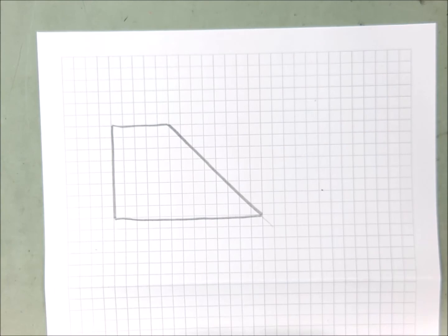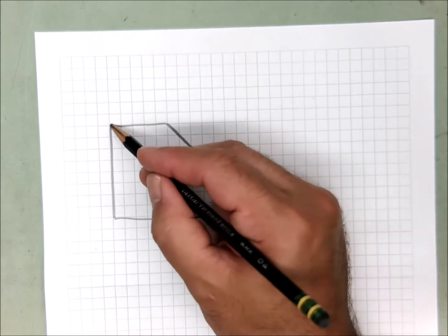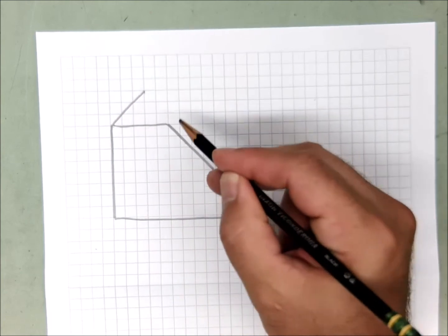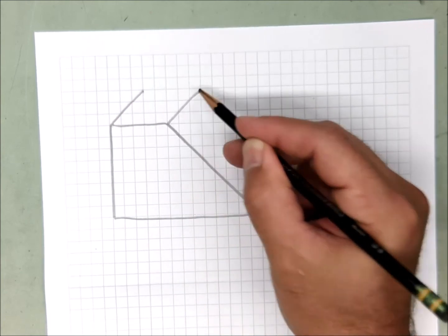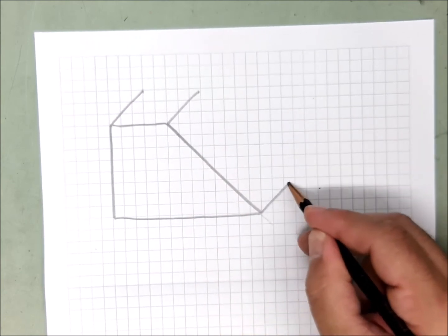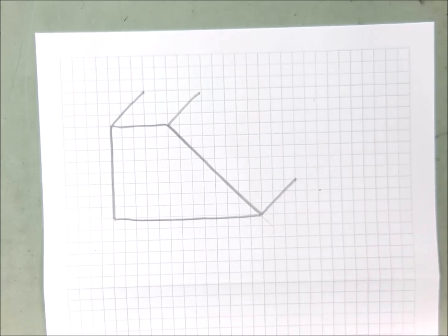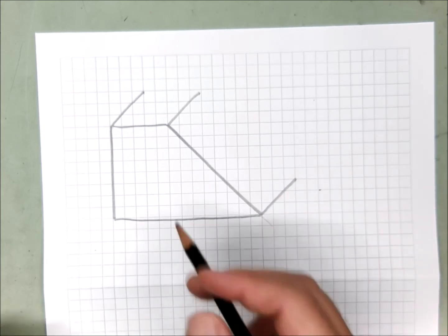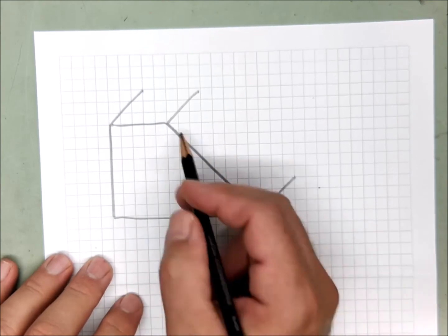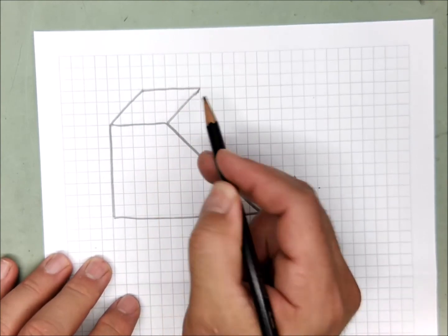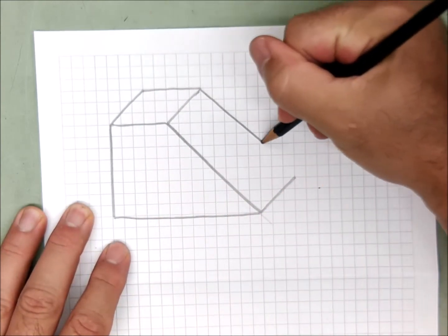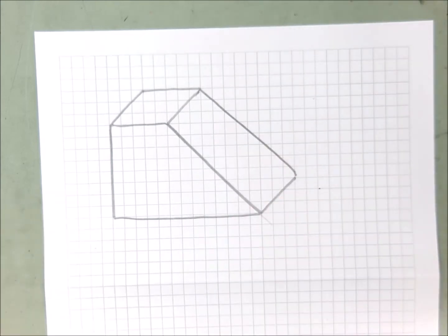There we go. Alright, so how do we oblique this guy? Nothing different. 1, 2, 3. 1, 2, 3. 1, 2, 3. Those are our 3 obliqued 45-degree lines. And then again, copy the front elements to the back. Alright, and there is our wedge, the little flat spot on top in oblique.